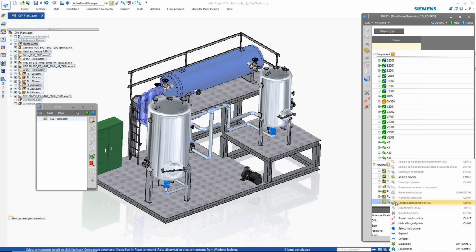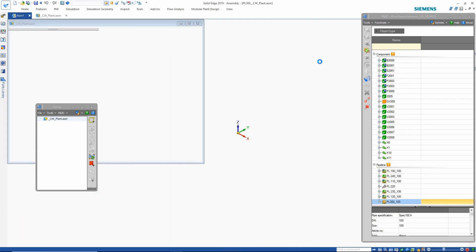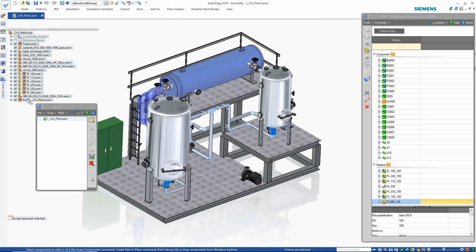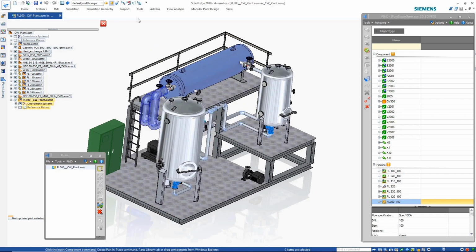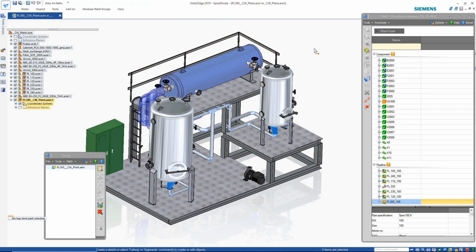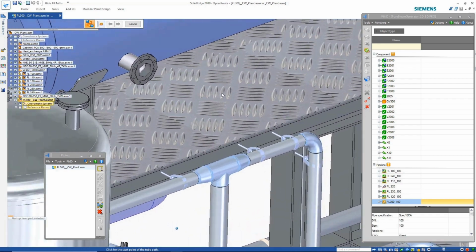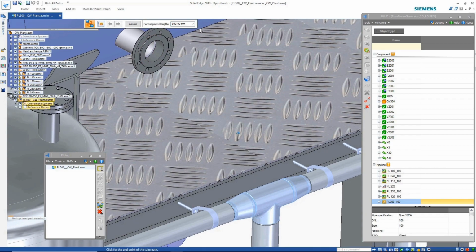What's very nice is there's some cool features that are available in Solid Edge, and there's a feature called Express Route, which allows us to actually automatically select the best path from beginning to end. And we'll do that now, and we'll select our pipeline like we have over there. And from Tools, we choose Express Route. And from the Quick Select, we'll choose Path Express. And that actually automatically, once you've selected the right point in the flange, will select the right path where it needs to connect to.